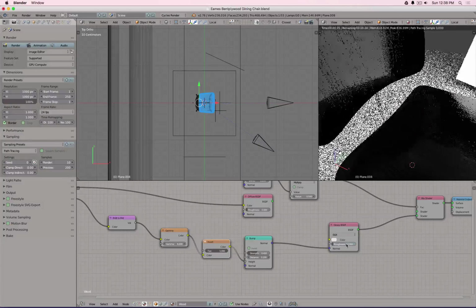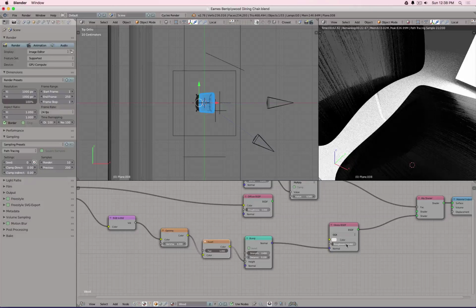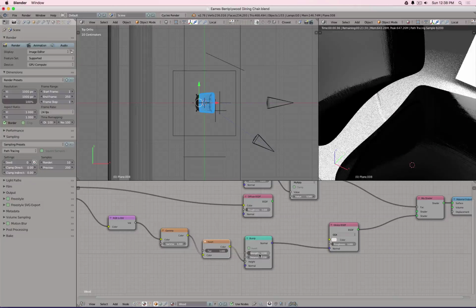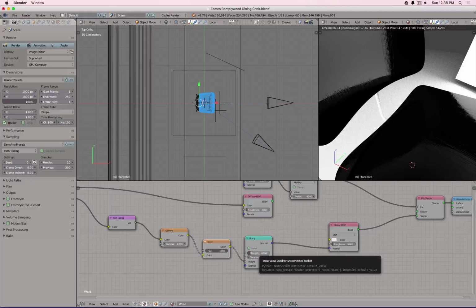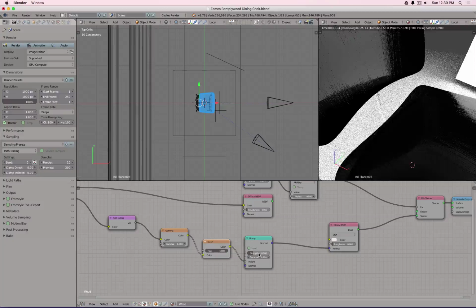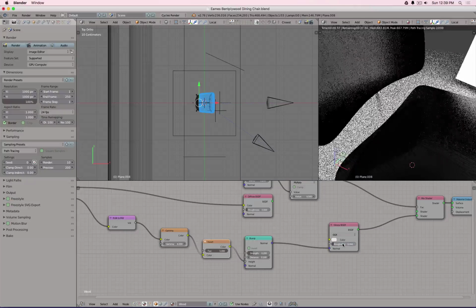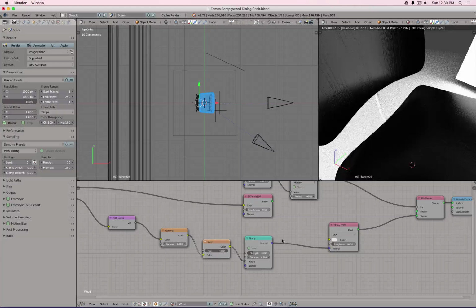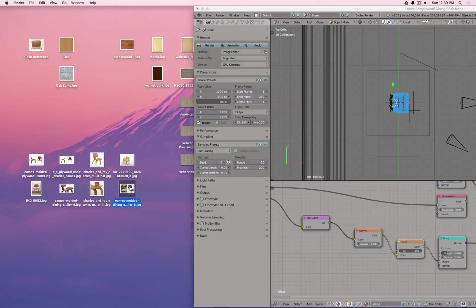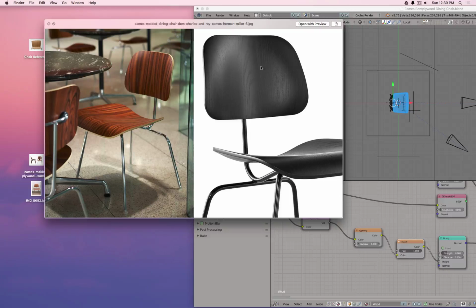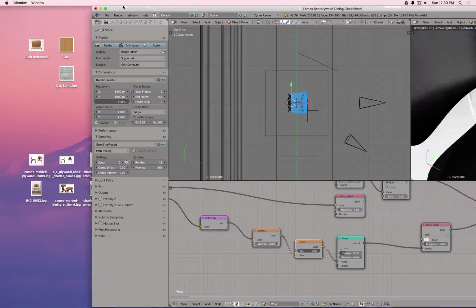If we set this to 0, it looks super plastic, and then there are some grooves cut in. Or we can fine tune this for smaller bump mapping values, so strength 0.1, 0.2, yeah, and this is too reflective, so 0.05. We actually get something that's very close to this image here.